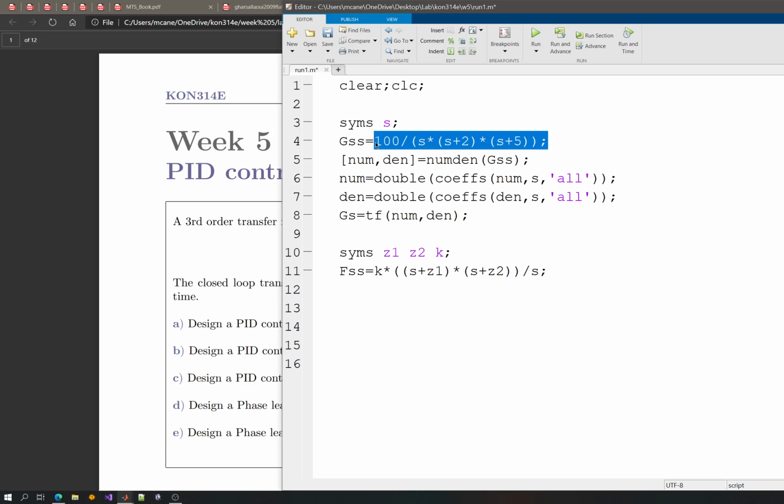It's marginally stable, by the way, because it is an integrator. And if you apply a step response, you will see that it will be a ramp function, which means that the ramp function isn't bounded, which means that this is not stable in that sense. So I cannot cancel, and I should not cancel a pole at the origin. It's not a good idea.